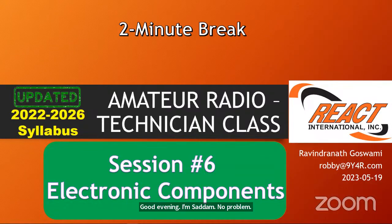Okay, so Nadia, how do you differentiate whether the transistor is acting as an amplifier or a switch in a schematic? That's an excellent question. So we would have presented a side-by-side comparison of two circuits in the previous class, where you will see the setup where a transistor is used in an amplification application versus a switch application. The difference really is how it is biased, or how you set up the transistor, the voltages that you apply to the various leads or electrodes of the transistor.